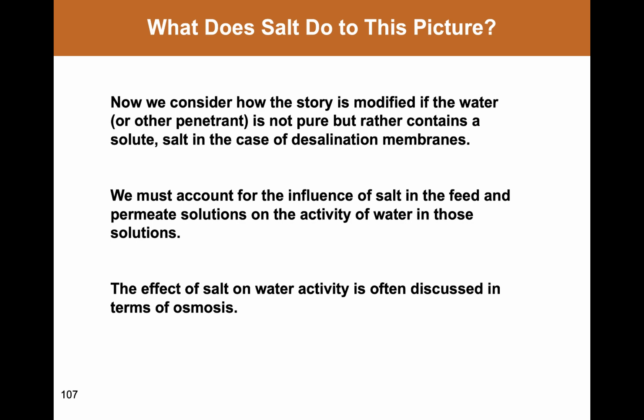And it turns out that it has actually very little impact on the general nature of what we have discussed. The only thing the salt does is act to modulate the thermodynamic activity of the penetrant that is in the feed and permeate solution surrounding the membrane. Essentially, for all intents and purposes, for desalination, the presence of the salt does little to change the actual transport of water inside the membrane.